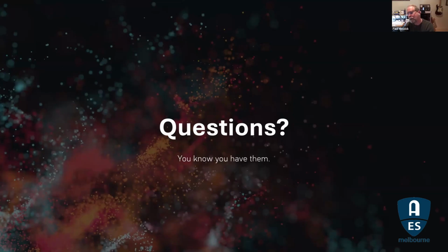If you're having a balanced input using a pair of op amps, that means you've got 2 active components in the signal path instead of 1. The only mitigating factor is you're dividing the effective resistance of the source by 2. Mm-hmm. And then with the gain, the noise adding on power and gain adding voltage wise, you can end up back at the same point.